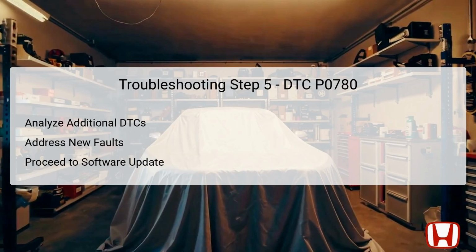Conversely, if no additional trouble codes are identified, the next action is to check if the powertrain control module, PCM, is equipped with the latest software version. Should the PCM lack an update, the technician should proceed with updating this software. If the DTC P0780 disappears post-update, it signifies successful resolution. But if it persists, substituting the PCM with a known good unit would be necessary, guiding toward the concluding steps